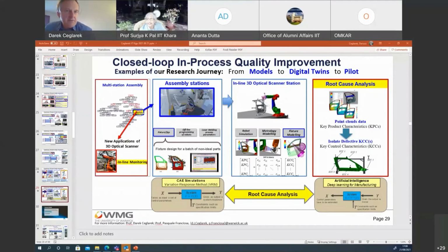And then uncertainty, meaning we already know all the parameters. With imprecision, I don't know something, for example the parameters. With uncertainty, we know all the parameters, but we do not know the variation range. So there is some uncertainty in terms of the variation of the parameters, and we are considering that variation on a couple of levels. One level was part variation. We do not assume that parts come in ideal, design nominal, but we consider the variation of the components. If we know the variation, then we include it. If not, we simulate the variation as well.